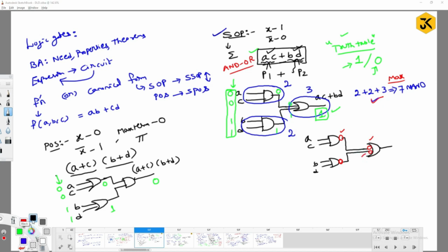Yes. Now if you look into this particular syntax, what is the meaning of this? Try to observe. If I have two inputs, x and y, and I make it like this, the meaning is x complement plus y complement. So the input is x complement plus y complement. According to De Morgan's law, I can write it as xy whole complement. Yes, xy whole complement, right?